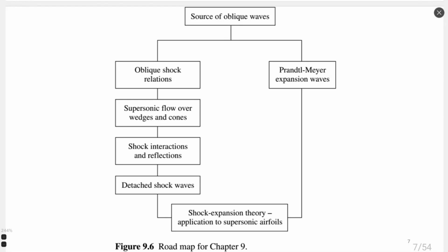I will show you how to calculate properties of the flow on shockwave interaction. It's a very interesting question, and it is not linear and cannot be calculated in a fast way, but it's not so difficult, so it can be reviewed analytically how two or several shockwaves would interact between themselves. And it's a very important application when we design aerospace structures that have several shockwaves intersecting with each other.